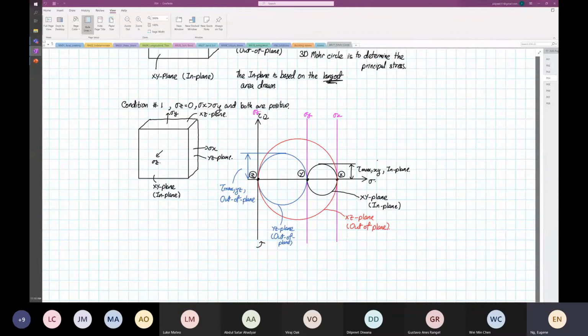Now this is what we call the true design work. What we have learned before is fundamentals. This is incorporating normal stress and shear stress. The normal stress we calculate by bending moment. Shear stress is due to shearing stress, and it's also due to torsion. Now we combine everything down here. The purpose is to determine the principal stress. Then we can select true engineering material.